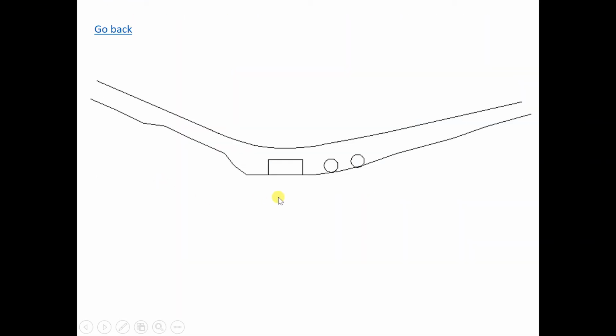Drainage, so we have to consider drainage as well. Make sure that the road is not at the sag, not too low. It must be above the flooding, above the highest flood. It depends whether it's designed for once in 20 years, or 1 in 50 years.